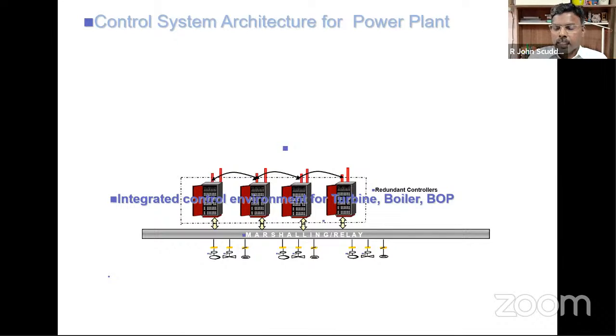And in the engineering station, you have typical function codes for receiving an analog input signal and making it into an analog tag so that it can be visibly seen in the HMI server.